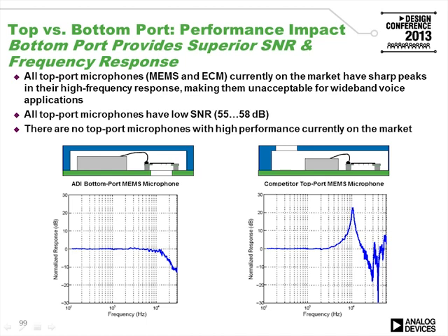So all top port microphones on the market currently have these sharp peaks in their high frequency response, and this makes them unusable for wideband voice applications. Top port microphones also have lower SNRs, or signal to noise ratios, than what we achieve with our bottom port microphones, and to date there are no top port microphones with high performance that are currently on the market.